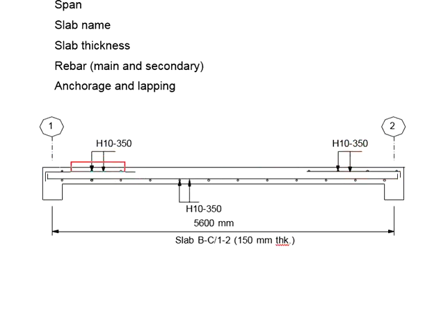Regarding the arrangement of the reinforcement, you know that the main reinforcement will be in these directions. When you determine the effective depth, we are referring from the top surface of the slab to the centroid of the reinforcement. When you do the calculations for the negative moment at the support, the effective depth is reversed.